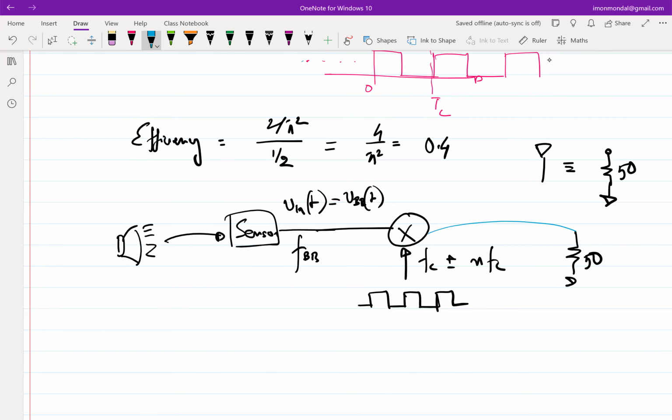For any type of sensor or actuator, when the domains differ, the only thing that is common is power. So you do E cross H in the EM domain, Poynting vector and so on. Then you get some power. You equate that to I times V in the circuit domain.